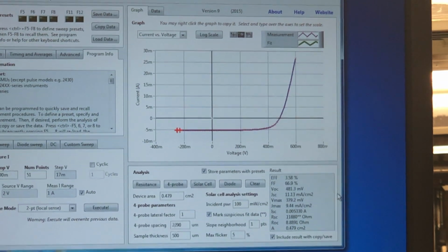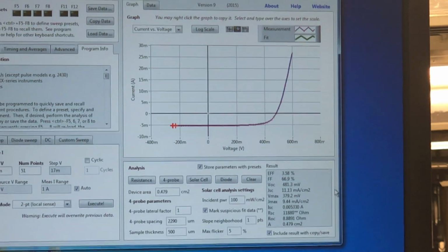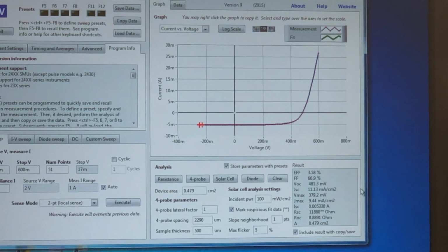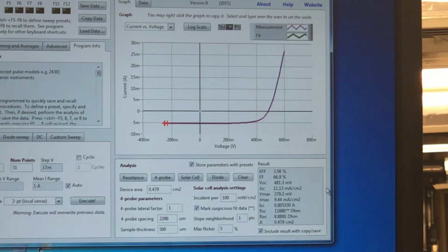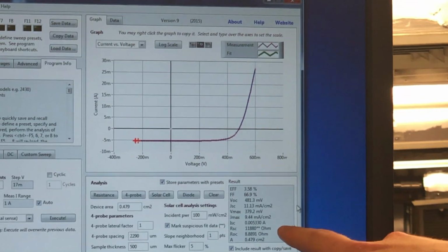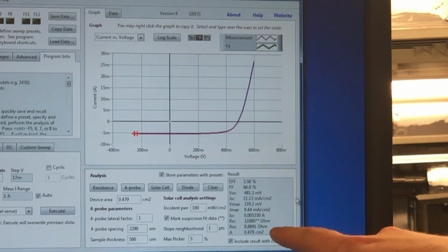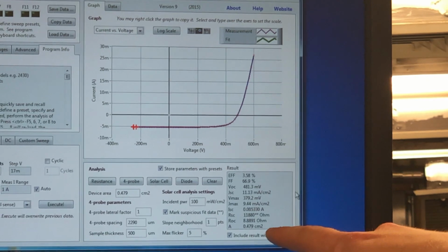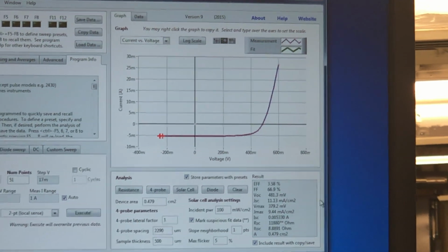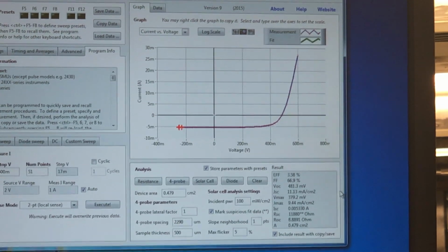So just correct for that. And what you do. So we're a little bit off. The lamp's not perfect, but we're just going to consider it okay because it's a little hard to tweak this one. The ISC of this curve is 5.3 milliamps. We should be getting a current of 4.6 milliamps, so it's a little bit high. But the efficiency is a little bit lower, which could be due to how we're probing it.